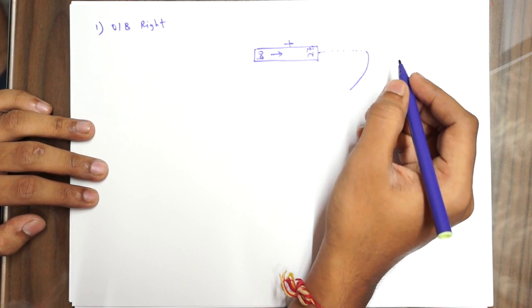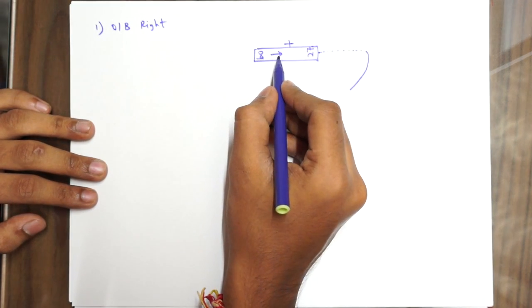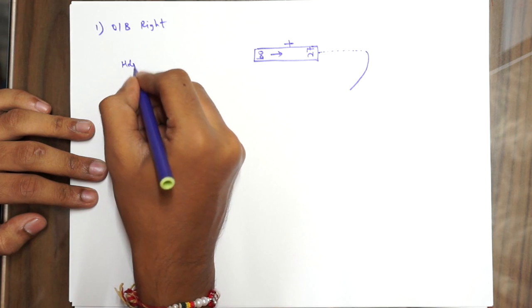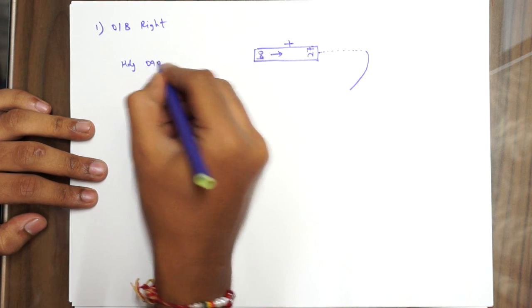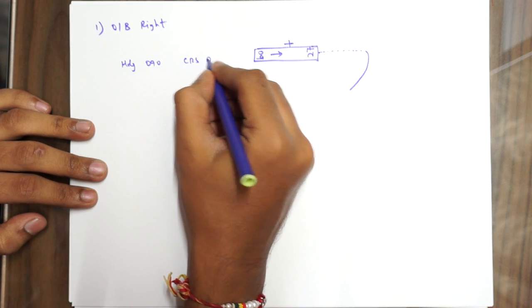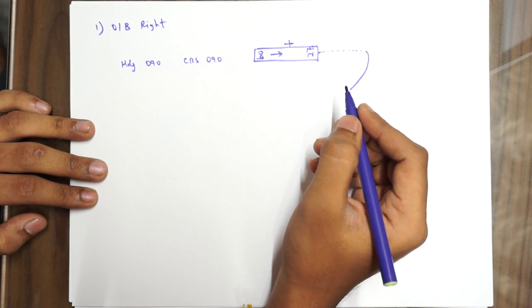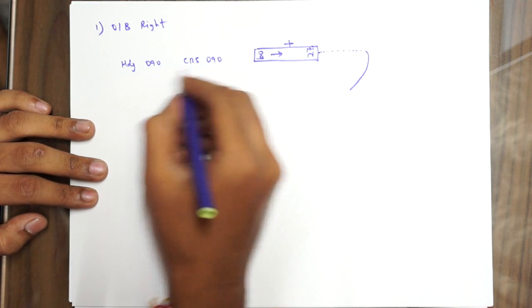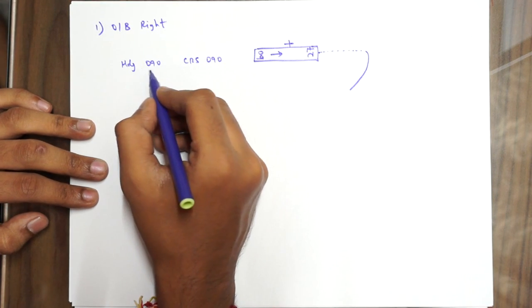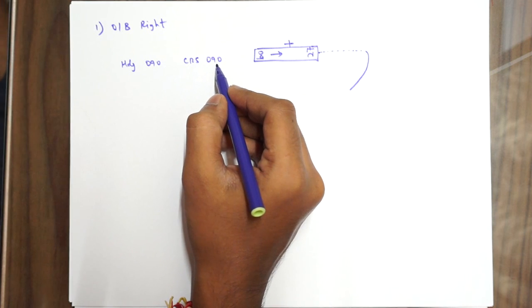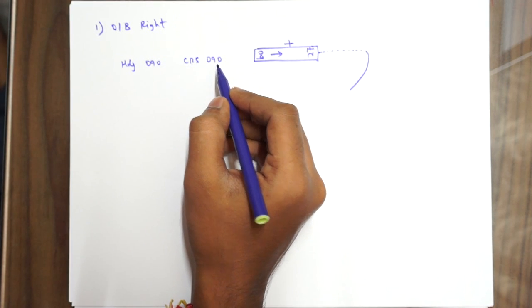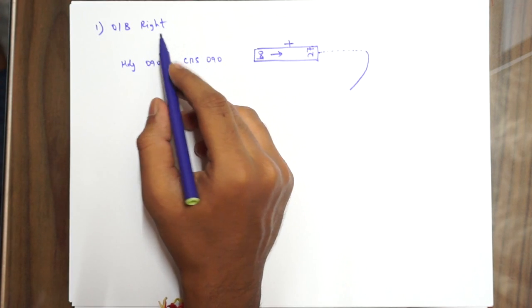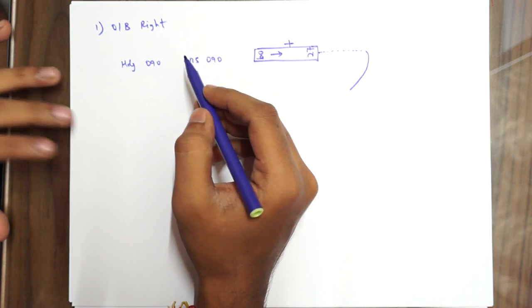Now the procedure is simple. At first your heading is 090, your course is also 090 initially. When this is outbound, your heading and course are the same. If you remember the radial interception video, I mentioned heading and course will be the same on any sort of outbound.